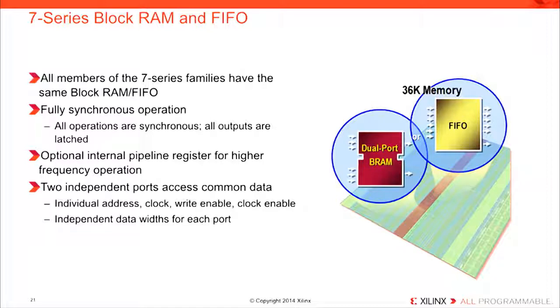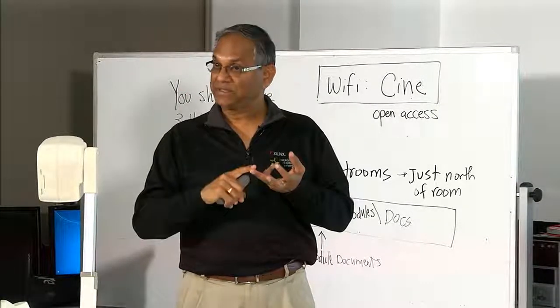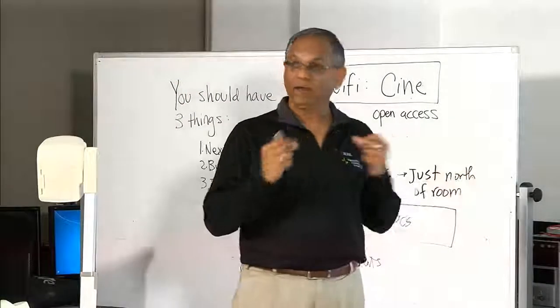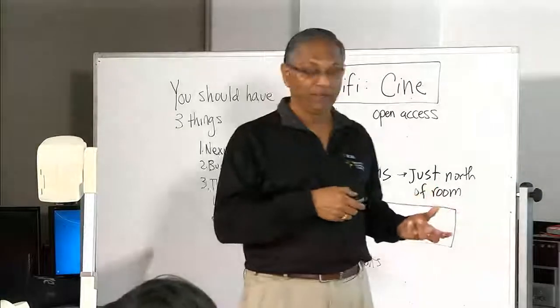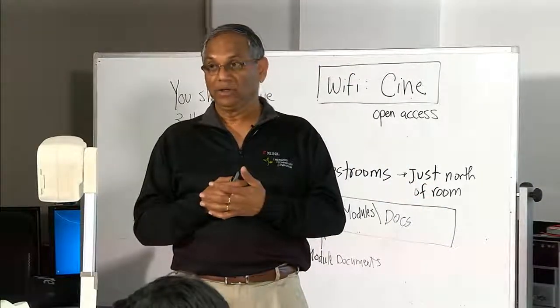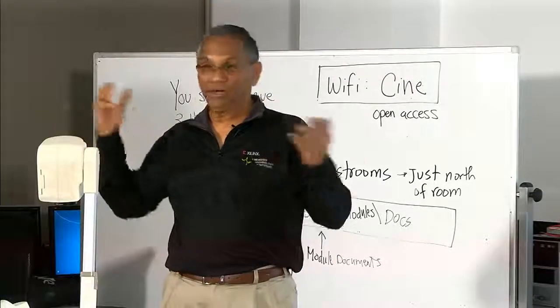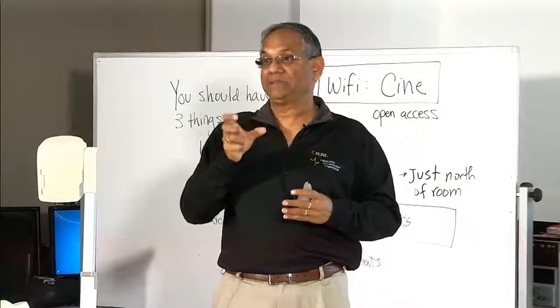The dual port block memory would look like you have 2 different ports, each with an individual clock signal, clock enable signal, write enable signal, and output enable signal. Addresses, data input port and data output port each have their own. They can run at different clock speeds, and they can run at different widths. So, port A, for example, can be 4-bit input and you may be reading 8-bit output on port B, or 32-bit output, because internally it uses the same memory core.